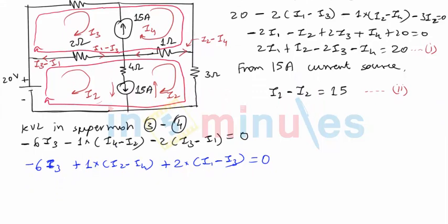So henceforth choice will be yours. If you want to define two different currents and write voltage drop accordingly, you can do that, or you can stick to the same current. Whenever you are in the direction of current, drop is negative, and whenever you are in the opposite direction of current, drop will be positive. Okay, now let's simplify this. First I write down I1 term, plus 2 I1, then I2, which is here, plus I2. Next is minus 6 minus 2, which is minus 8 I3, and minus I4 equal to 0.